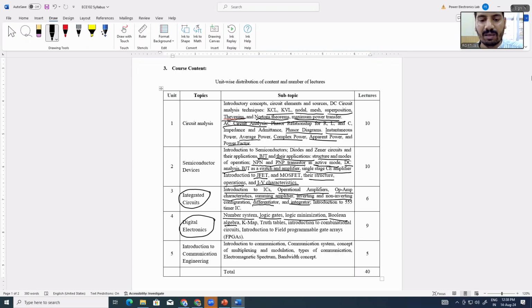These are the complements of OR gate and AND gate. The complement of OR is NOR gate. The complement of AND is NAND gate. So there are basically 5 types of gates, and additionally there are 2 other gates also, XOR gate and XNOR gate. NAND and NOR gates are also called universal gates.